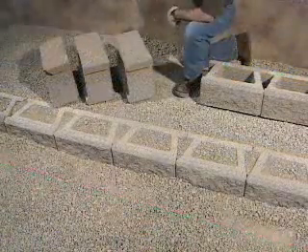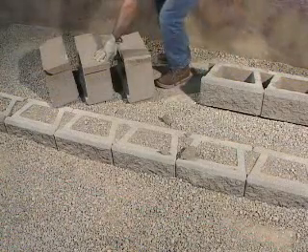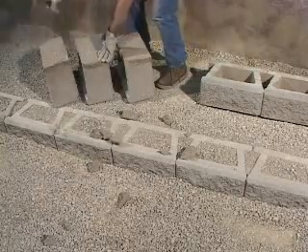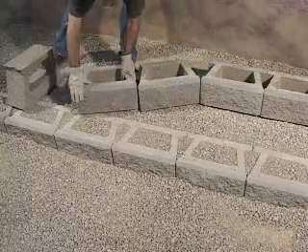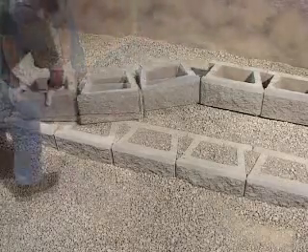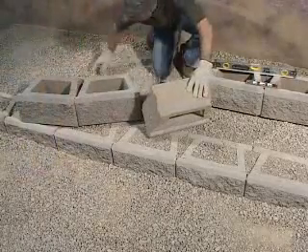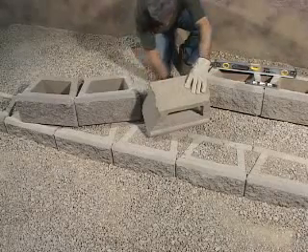To continue building your wall out from the stair location, break the wings off the blocks by striking the back of the wing with a hammer to obtain a clean break. Then place the blocks tight together, following the layout on the approved plans, making adjustments as necessary. You can place a small amount of wall rock under the blocks to level them, then check again for level and make adjustments if necessary.